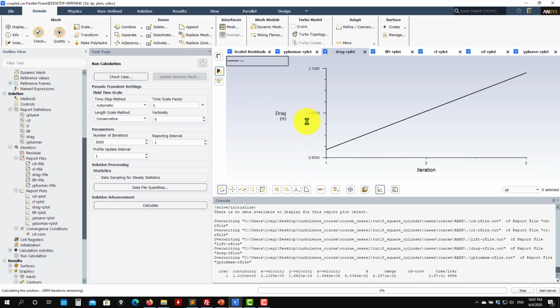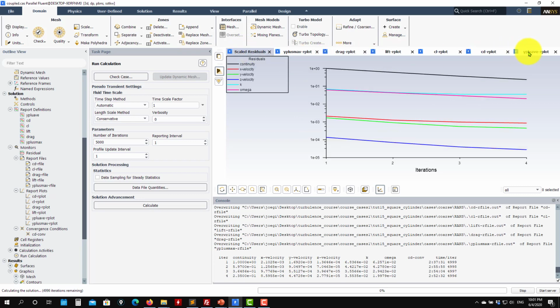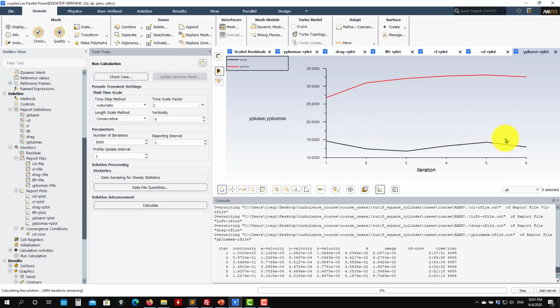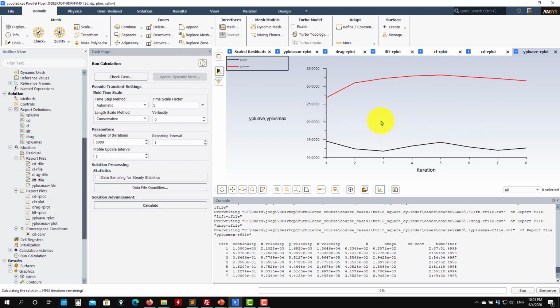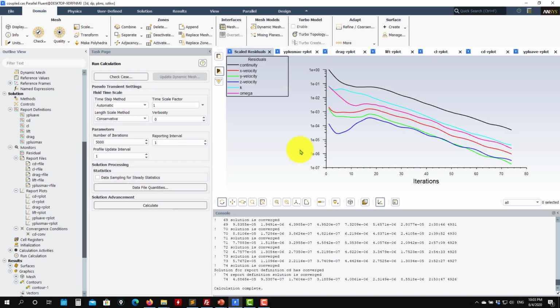So starting from that condition, it will start to iterate, and see that here we are plotting the two, the maximum and the average. Let's see how many iterations it takes in this case now. Okay, in my case, I arrived at a converged solution. See that now both monitors converged at about 74, which is faster. You can see that it's faster than the previous one. It might not be much, but in some cases you will feel the difference.